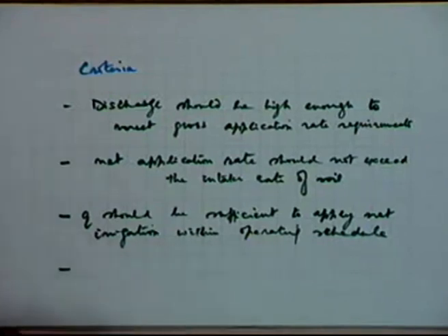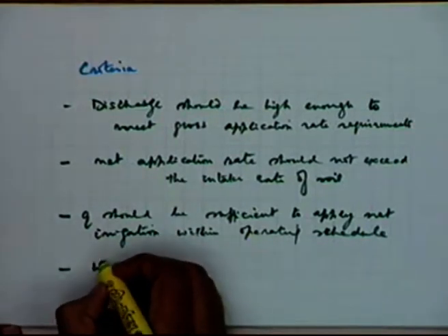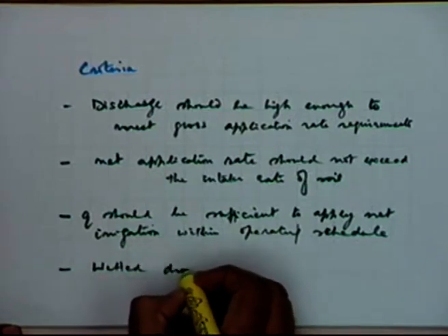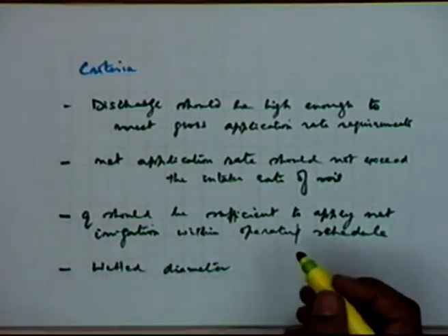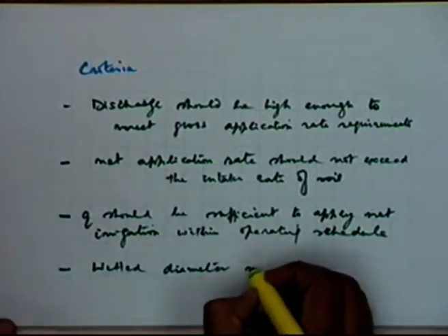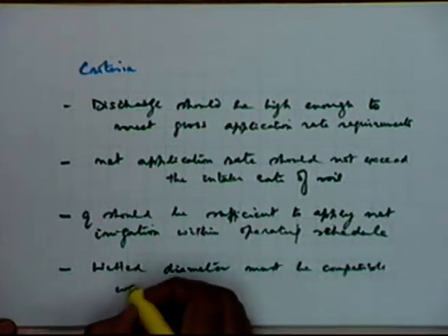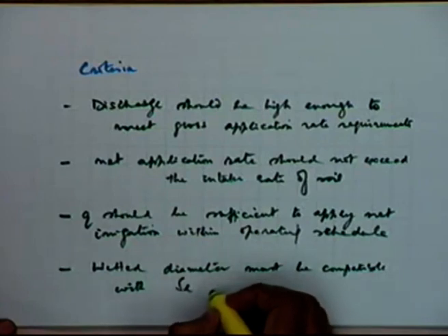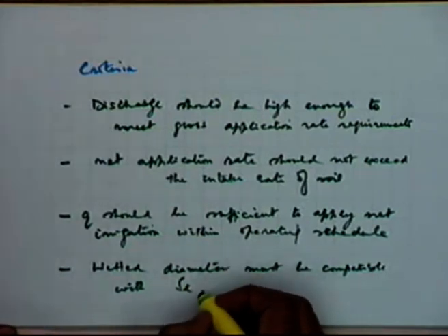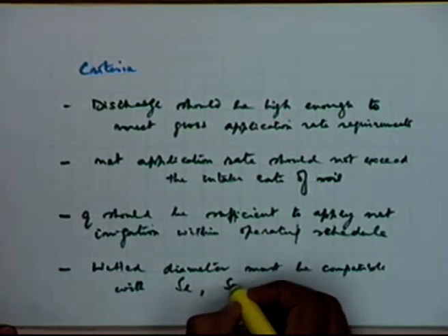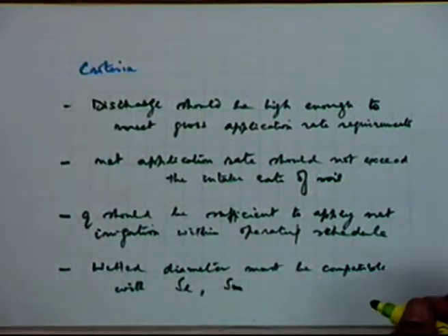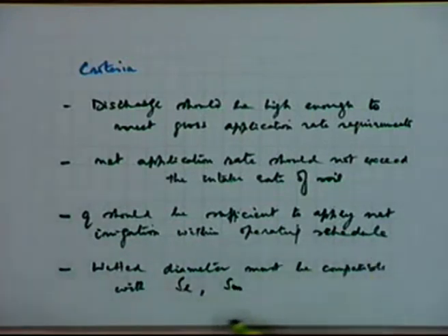Then you have another requirement that the wetted diameter must be compatible with the spacing, the main line spacing and the lateral spacing. Because again, how much wetted diameter you are going to have is a function of the nozzle selection.